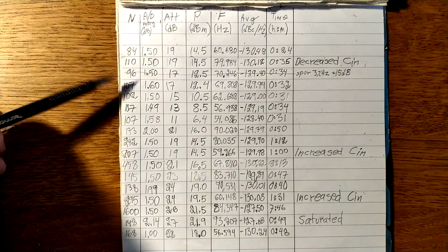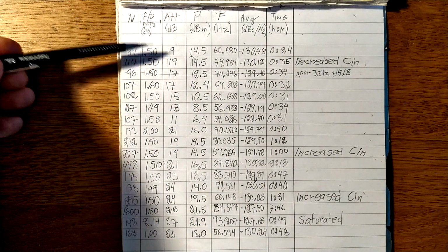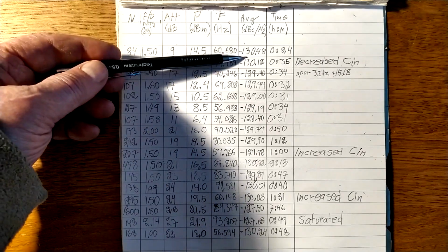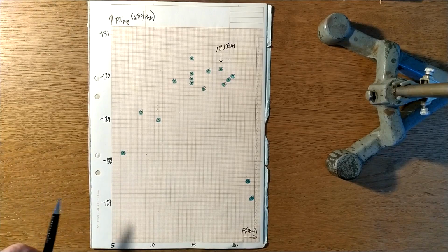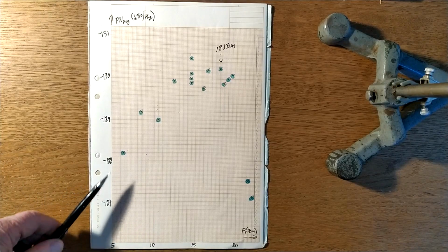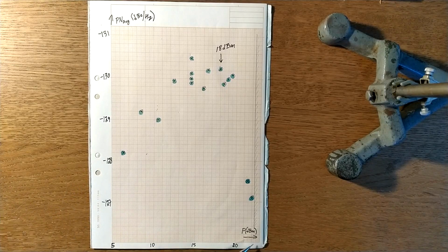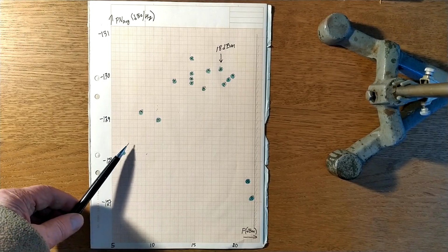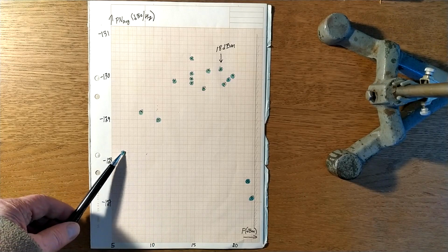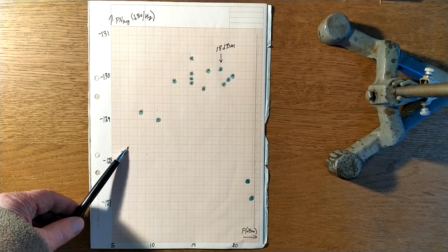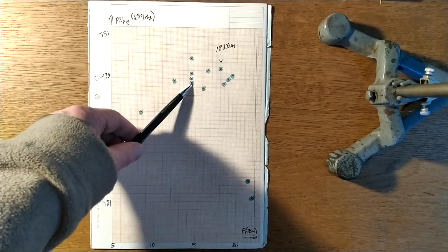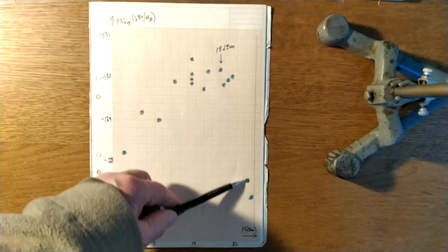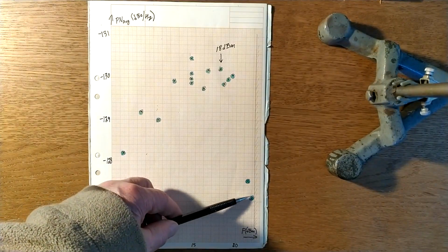There is of course a statistical uncertainty, particularly the very first point, only 84 averages, so it is a little bit high. When I plot the data points from 5 to 22 dBm, I see a curve that looks quite reasonable. At very low power levels there is a loss of performance, then it seems to be fairly flat here, and then it drops very fast when it approaches saturation.